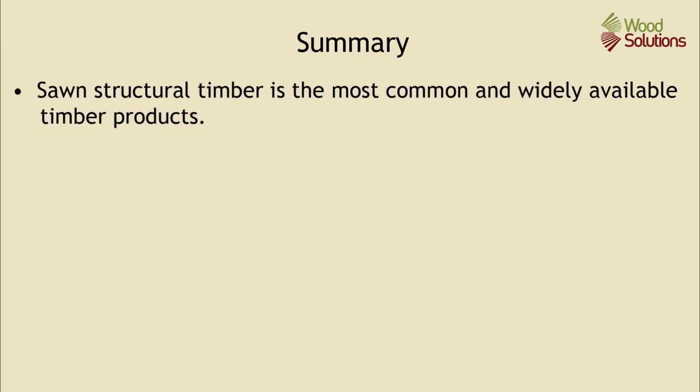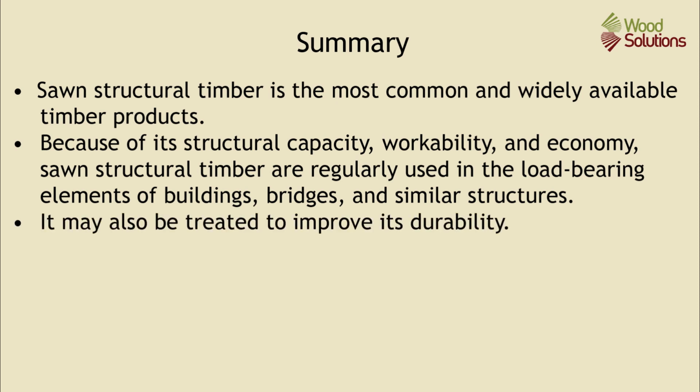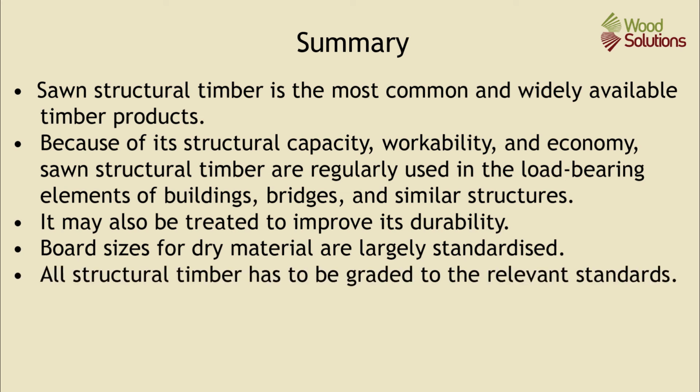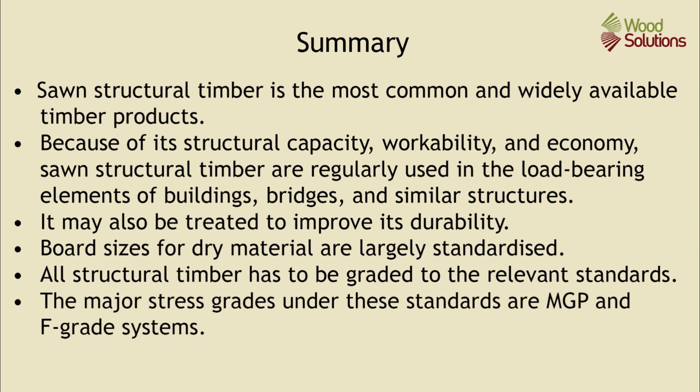In summary to this presentation, sawn structural timber is the most common and widely available timber product. Because of its structural capacity, workability and economy, sawn structural timber is regularly used in the load-bearing elements of bridges, buildings and similar structures. It may also be treated to improve its durability. Board sizes for seasoned, hardwood and softwood are largely standardised. All structural timber has to be graded to the relevant standard, and the major stress grade systems under these standards are F grades and MGP grades.